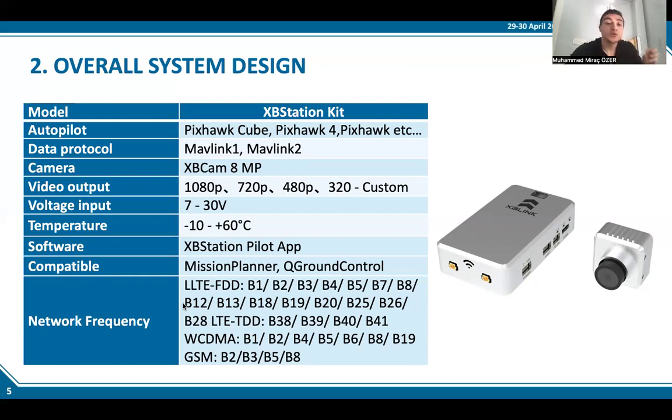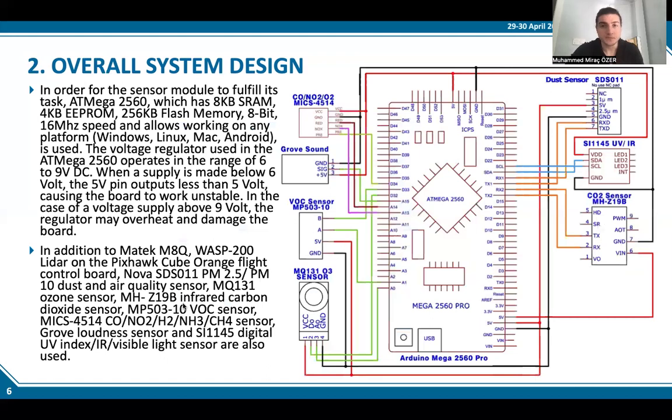Easy to use. In order to monitor the vehicle during the flight and the imaging system, the XP-Link 4G LTE module, which provides IoT communication and control connected to the flight control system, has an HDMI interface that offers 8 megapixel, 160-degree ultra-wide angle, full HD video shooting quality and the lowest delay in order to follow the drone during the atmospheric flight.